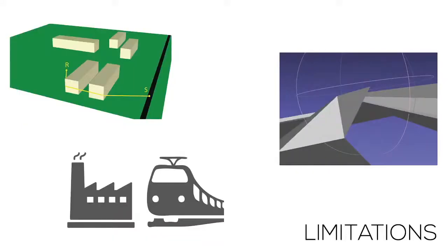We use different files in order to extract the propagation paths. However, these files can have a difference in precision, which in some cases causes a reflection to become invalid. We have tried to solve this by adding a tolerance, but this did not yet solve it and caused other topological inconsistencies. Therefore, it is not solved at the moment. This will in some cases cause slight errors when using incompatible input datasets. It could be solved by aligning the precision of the input datasets. Also, creating a constrained TIN, incorporating the ground types and buildings, has proven to be a challenge in specific cases. This sometimes resulted in an invalid terrain, as can be seen on the right side.